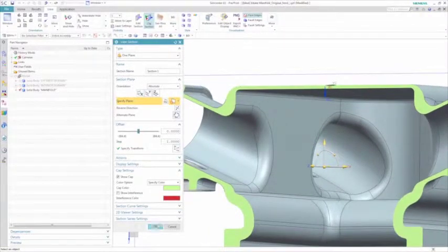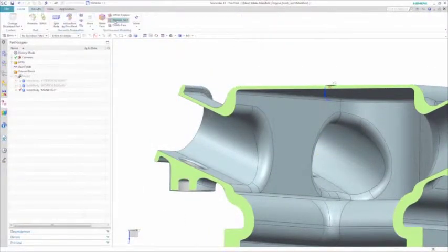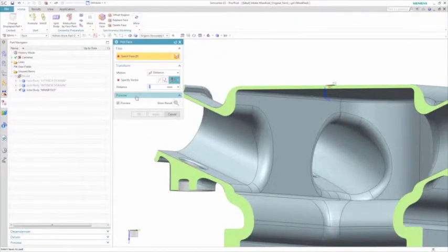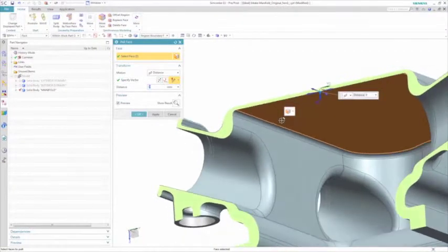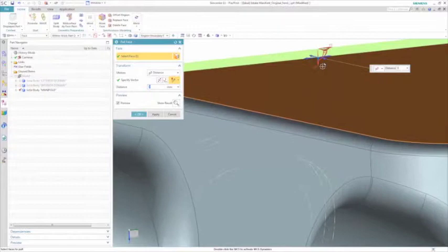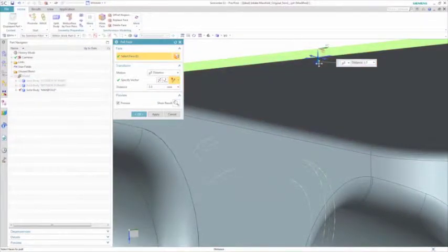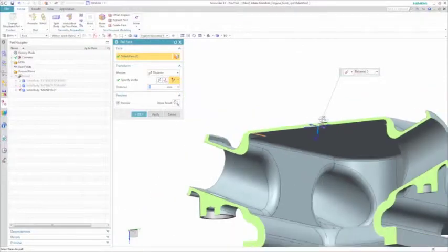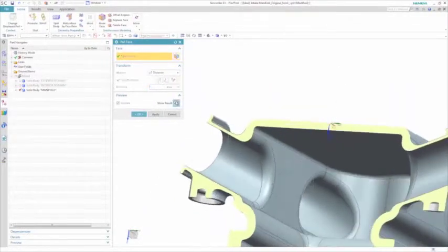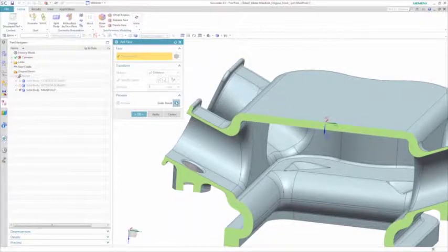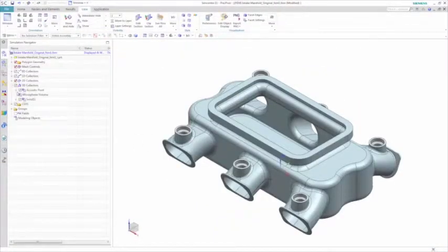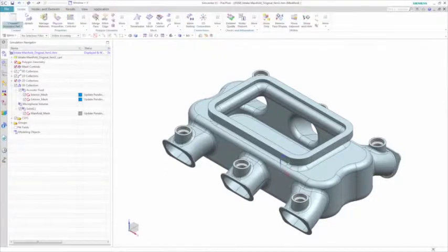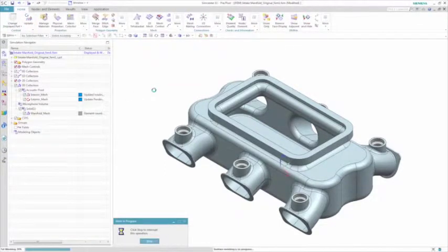of the manifold. One of the strengths of SimCenter 3D is that the analysis model is associated to the underlying geometry. This means you can quickly modify the geometry to test out a new design proposal and update the entire analysis model without having to manually rebuild it each time. This is possible on any geometry from any CAD source. What would otherwise be a cumbersome multi-day workflow in other tools is reduced to just minutes in SimCenter 3D. After modifying the geometry, you can then simply update the meshes and verify that this design change has propagated to the mesh.